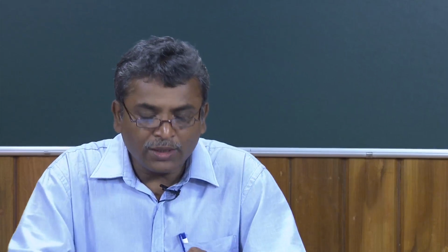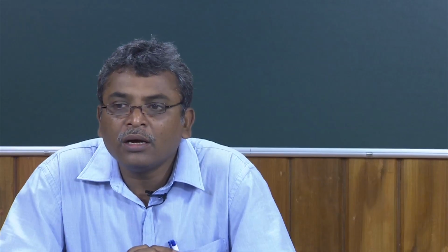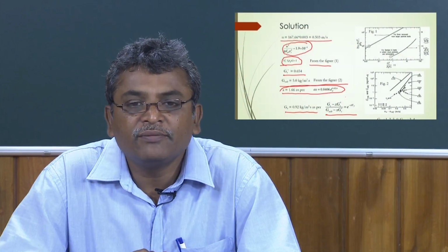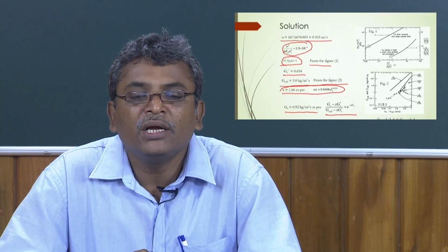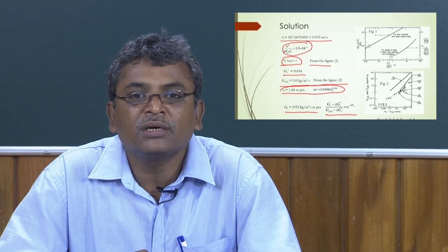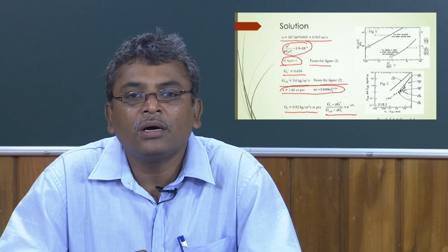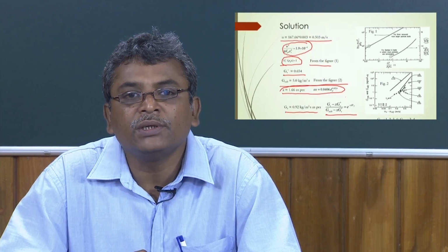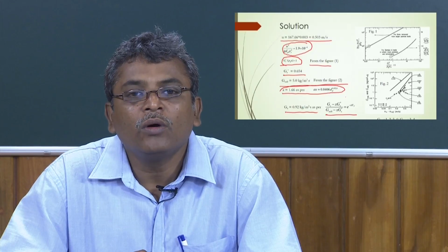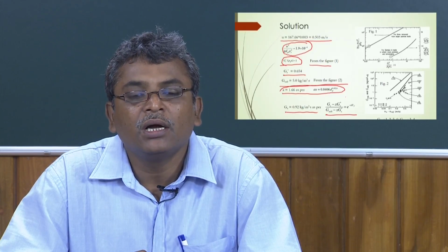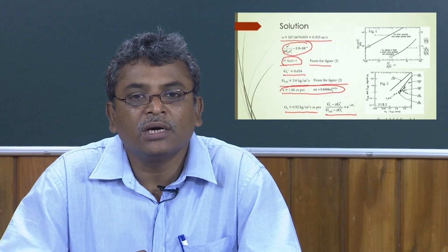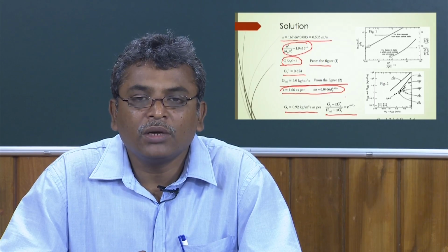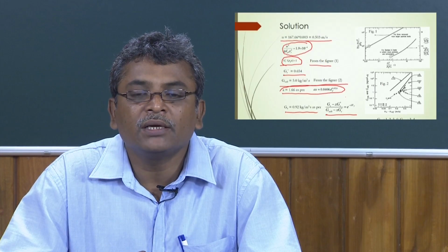So, what we have learned from this lecture is what the entrainment characteristics should be according to that model of entrainment, if we consider the phase phenomena inside the bed and the interaction of the phases, if there is any agglomeration and fines, and any interaction with the gaseous particles. Then based on their velocity, what will be the net flow of the fines that is entrained by the movement of the gas bubbles inside the freeboard, and how to express the profile of that entrainment characteristics.